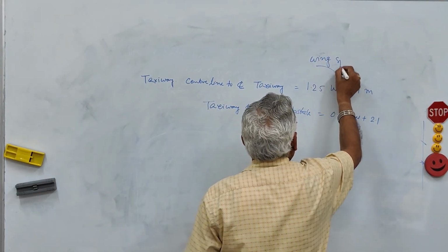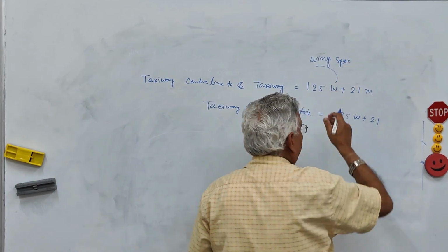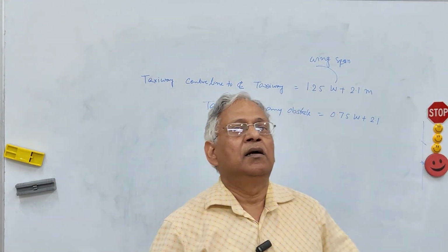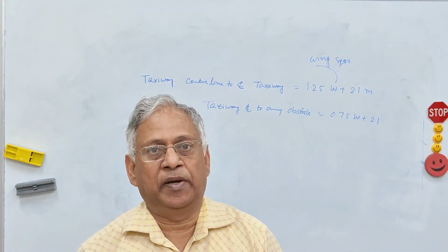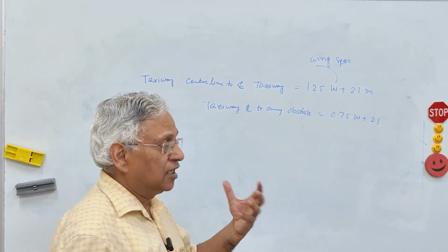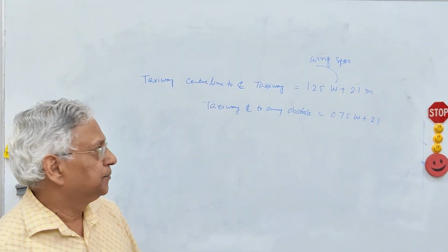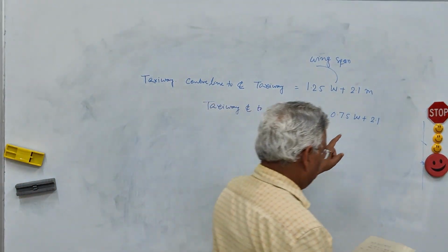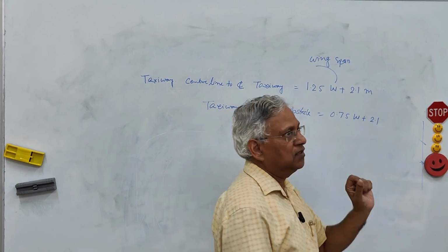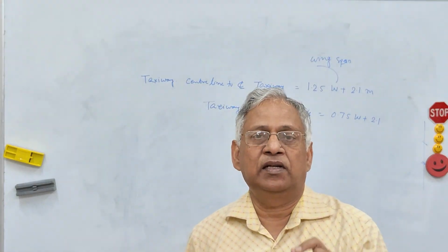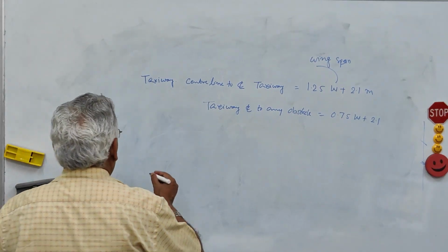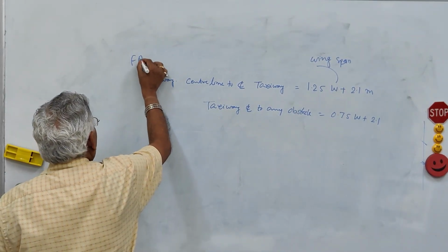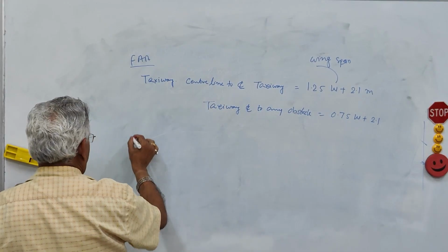And if there is a mixed type of aircraft operating at runway, we should take the longest or the widest wingspan, the maximum wingspan of the aircraft expected to serve the runway. And this 2.1 is called the safety margin. That is to consider the variability between the paths when they move on the taxiway. Now this is the equation given by FAA.